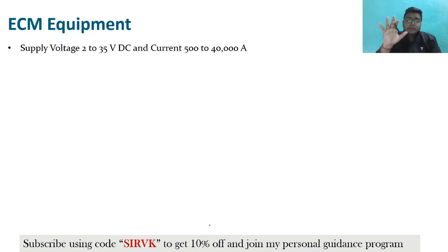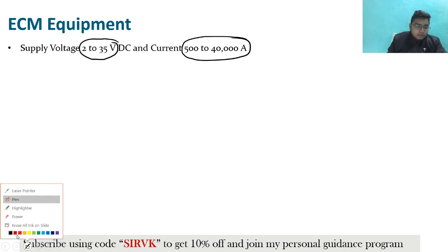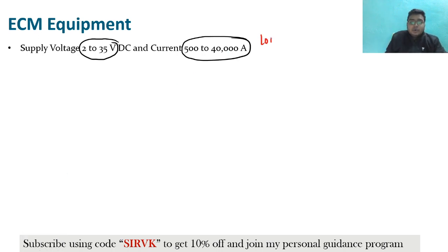So the principle of the ECM process is based on Faraday's law. And what is Faraday's law? We are going to talk about it briefly after some time. In the ECM process we give a very small amount of voltage and a very high amount of current, so that's why I have told you this process is known as low voltage, high current. Clear?